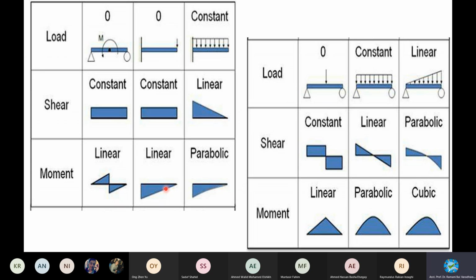Now the shear force. When you convert this moment into shear force, there is some value here, a reaction due to this moment, and there is some reaction here. That's why you have the values like this. And then when you come to loading of this type, there is a load and there is a reaction. When 20 is acting, there will be a 20 in the opposite direction, then only it is balanced. Altogether, you will have a positive value like this.